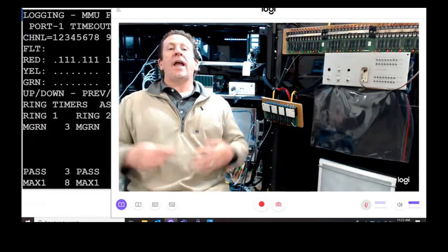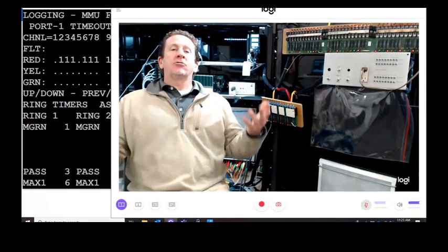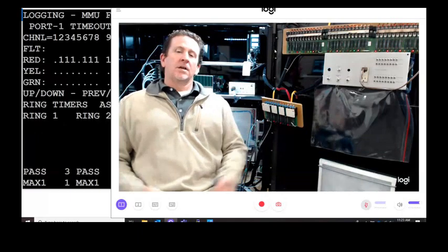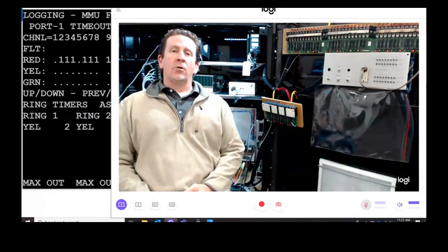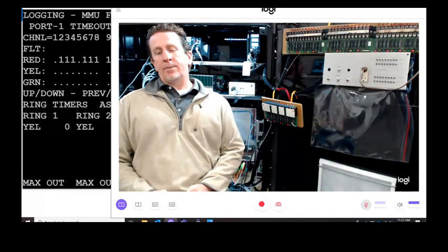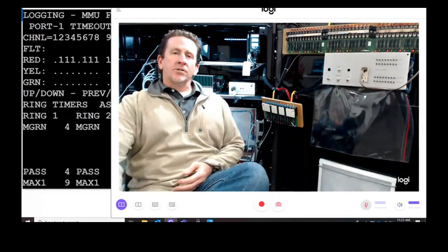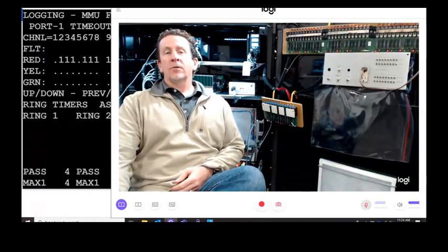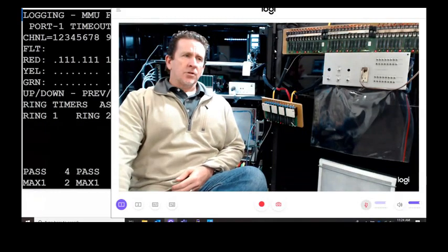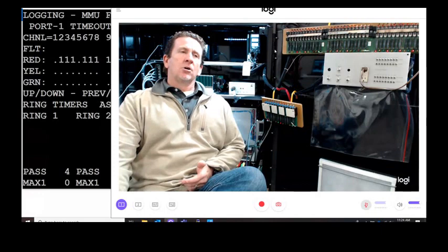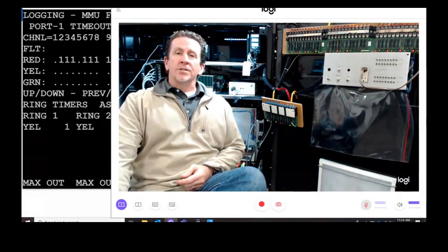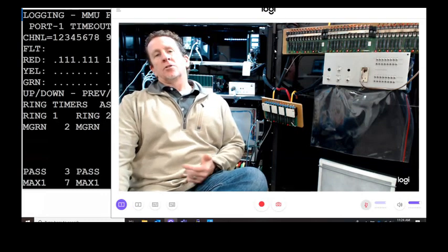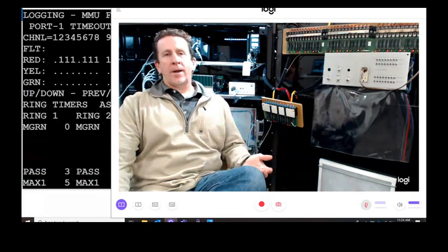It's just a failure that's been created due to some other kind of fail, red fail, port 1 fail, basically something that's not allowing the controller to power up. We're going to get a CVM fail. A lot of people will say, hey, I'm in CVM watchdog. Yep, you're in CVM watchdog because we're not running. As soon as we get the thing up and running, we'll clear the CVM. So that's what clearing the CVM means. We're correcting the fault, which is elsewhere, which is clearing the CVM fail, which is allowing the controller to initialize and get the controller to come back up and running.